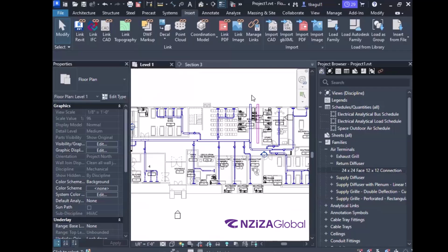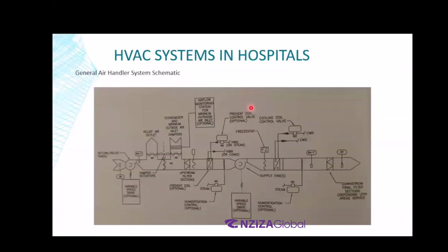Okay? Let's say from the calculation that we have gotten, minimum outdoor air changes per hour, for these 3 rooms, we require a minimum of 50 CFM. So if you have 785 coming from here and we have 50 CFM again getting added to it, it will just keep on increasing the pressure of the air handler as well as what is being supplied, right? It will become too high pressure. For that reason, we are relieving some air from here so that another 50 CFM, when it gets introduced into the air handler, we have the constant air going through.